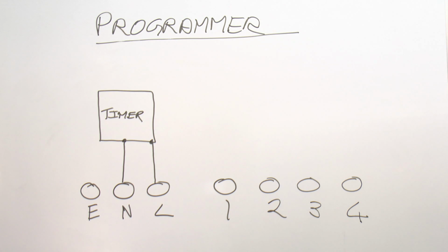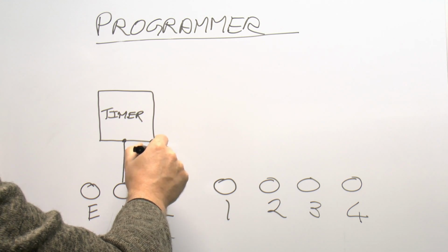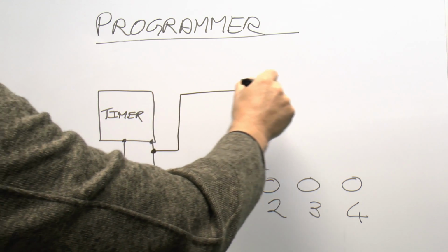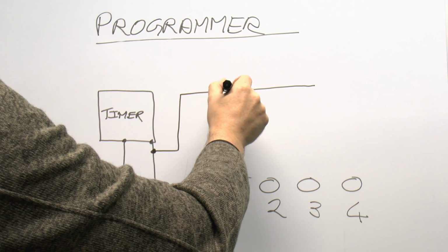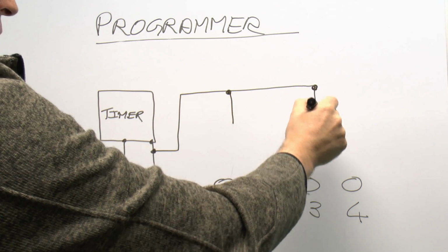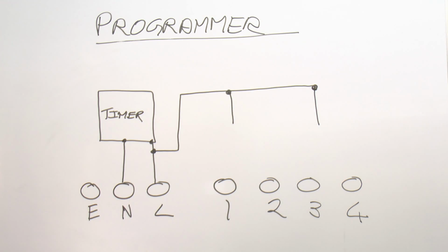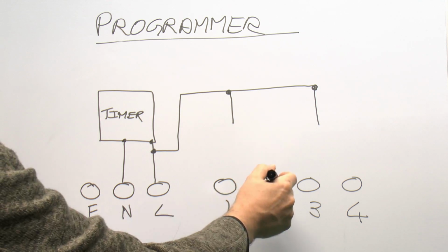And internally, it's basically a set of switches, connecting the incoming line here to the output terminals. So there'll be a contact coming down and another contact coming down over there. And the switching arrangement is that you've got a pair of terminals for the hot water, so one is on and one is off, and then the other pair of terminals is for the central heating, again that's on and off.